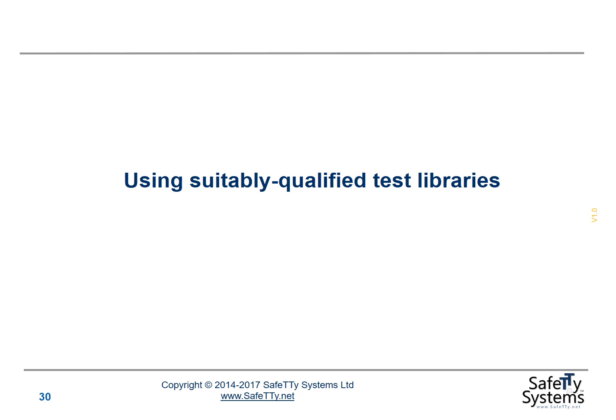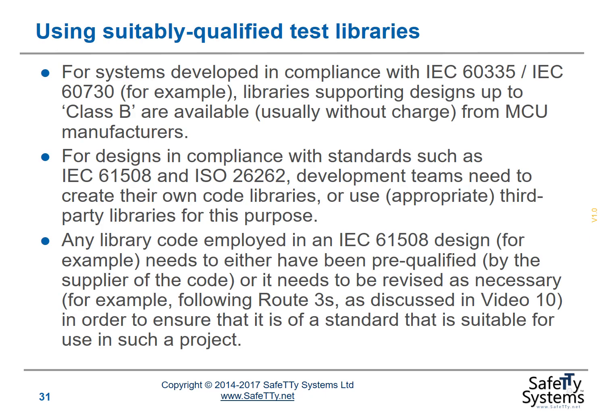When performing many of the tests we've just discussed, we need to use suitably qualified test libraries. For example, for systems developed in compliance with IEC 60335 or IEC 60730, libraries supporting designs up to Class B are available, usually without charge, from various MCU manufacturers. For designs in compliance with standards such as IEC 61508 and ISO 26262, development teams need to create their own libraries or use appropriate third-party libraries for this purpose.